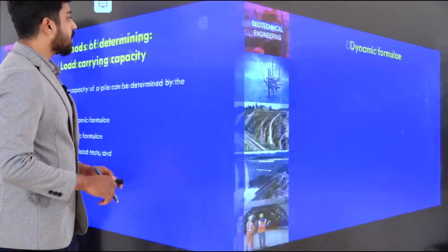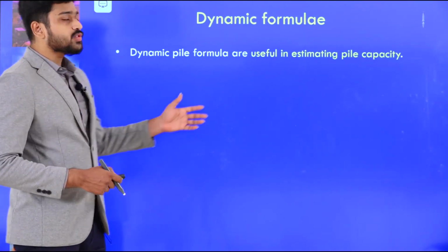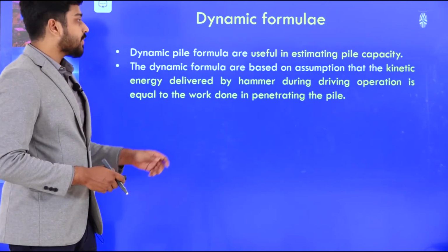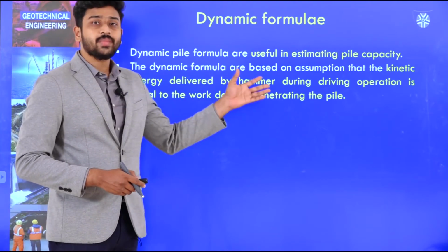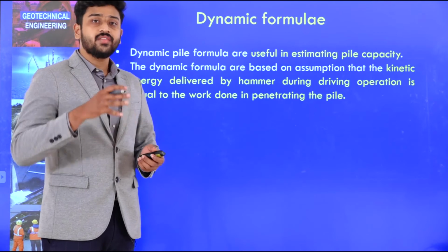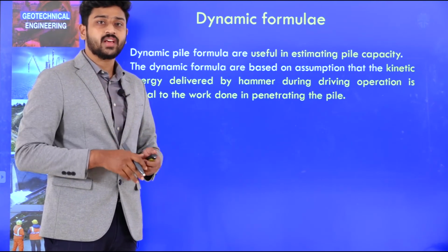The dynamic formula. So, coming to the dynamic formula, it is useful for estimation of pile capacity by dynamic means. The dynamic formula is completely based on the assumption that the entire kinetic energy that is delivered by a hammer, whenever we are using some external force, there will be some kinetic energy developed.